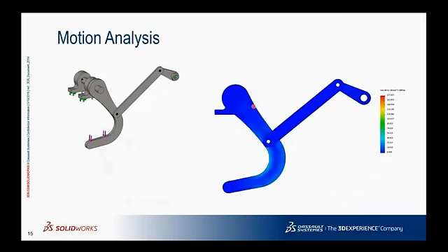And with the contact loads, we can then take those and do a structural analysis. So we can take the loads, apply them to the end of the hook, add a couple of pins to connect the linkage up, restrain it where the shaft is going to hold the crank and also where the bearings are, and then we get our nice stress analysis.